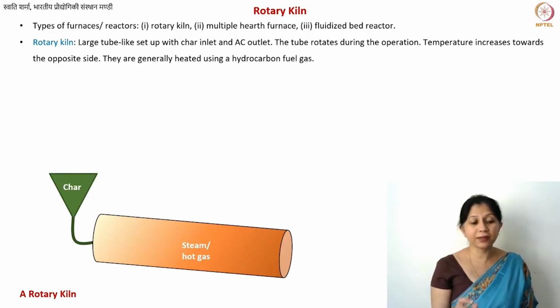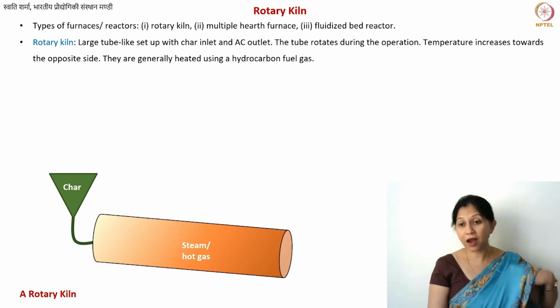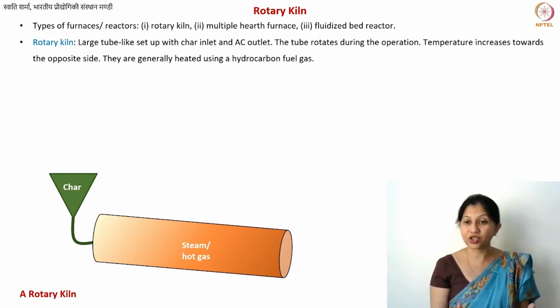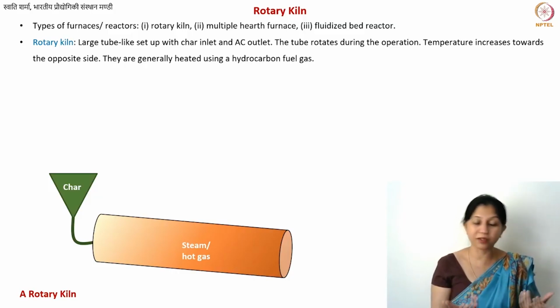What you have here is the starting material, because now we are talking only about activation and not about the carbonization process. So the starting material is your low purity carbon. Low purity carbons produced by the charring process are simply called chars. You will also hear the term biochar, because often these materials are prepared from biological, like plant materials, and in many cases nowadays, from waste materials.